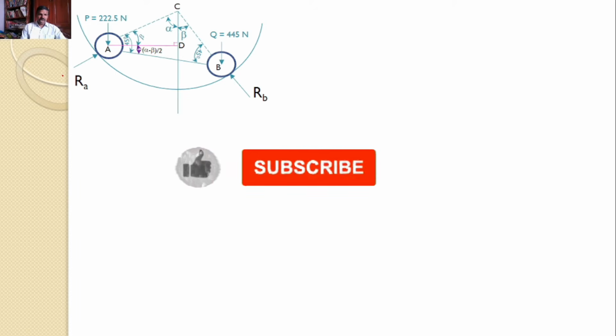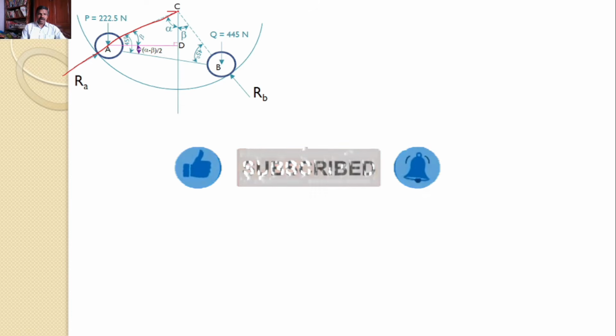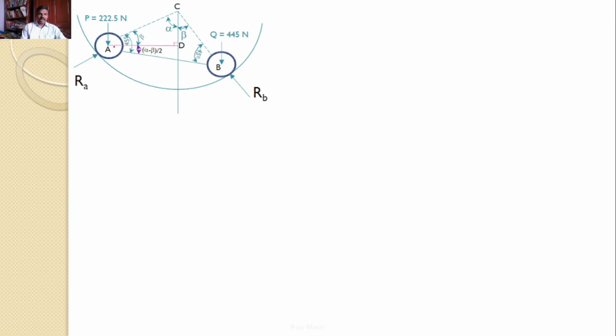The reaction force RA acts along the line AC because roller A is placed inside a circular ring, and the string force along AB, which is away from point A always, because we are assuming that the force in AB is tensile and acts away from the point of observation.